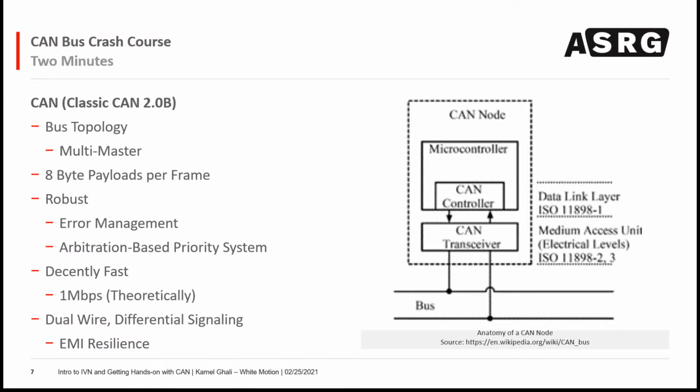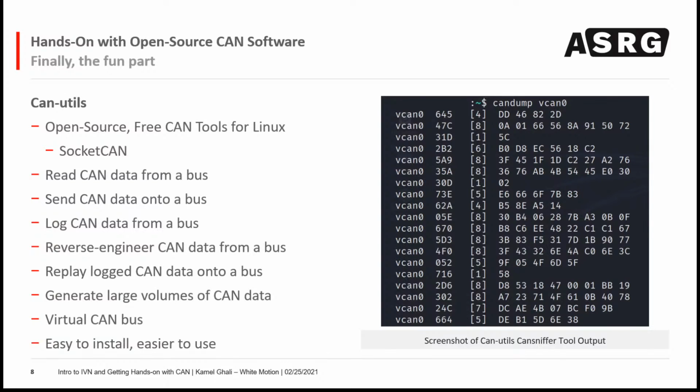A vehicle has a lot of different electronic components, a lot of different power cords, etc., moving throughout the vehicle. So a lot of times there's a lot of electromagnetic noise in the air, and this is just something you have to live with. You can't quite get rid of this. This is part of the universe. But because of the way differential signaling works, because one bus line drives up and the other one drives down, the difference should always stay the same as long as both wires are impacted by the EMI equally. This is quite an interesting topic, and I could talk more about this for another 30 minutes or so, but I do have a deadline I have to keep, so I'm going to be moving on from here, but I'm happy to answer any questions, of course, towards the end.